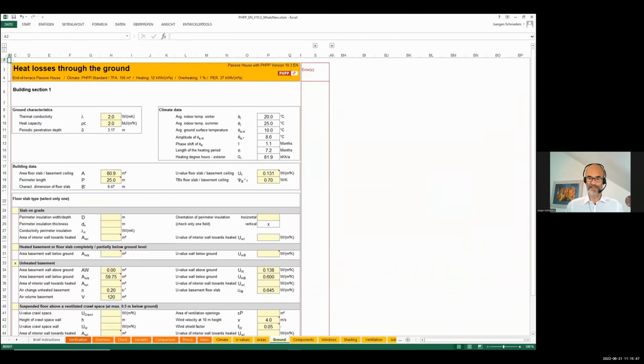That needs to be done twice because there may be different sections of ground which are calculated separately and which may have separate U values. So when this has been entered and then later on you change that U value and there's not a direct connection in Excel, you might get different entries and you would then get wrong results in the energy balance. So this now results in an error that is reported and that would show you where the wrong input is.